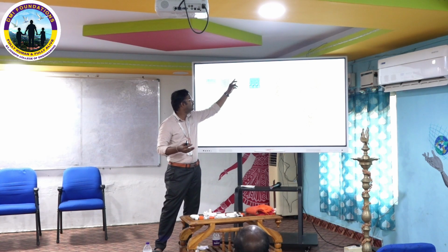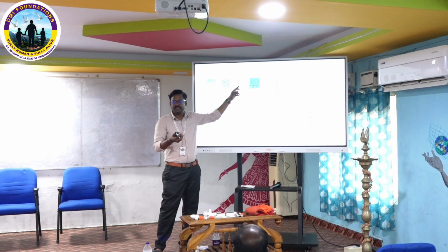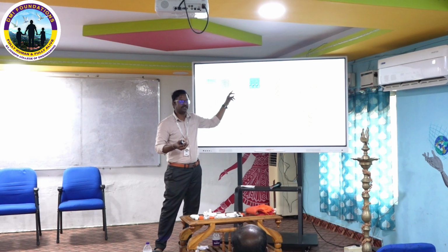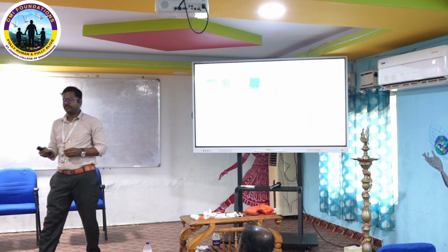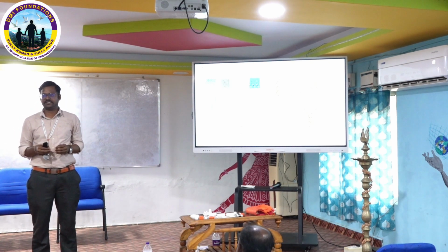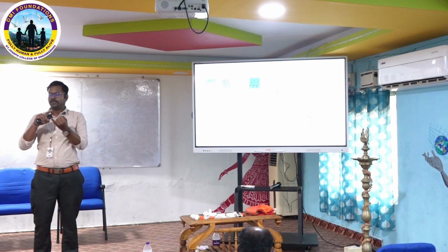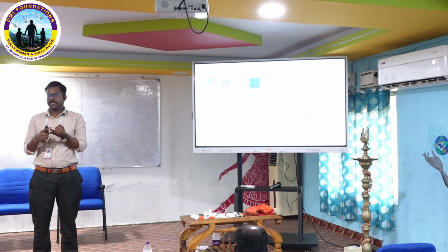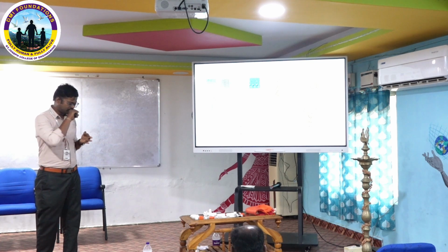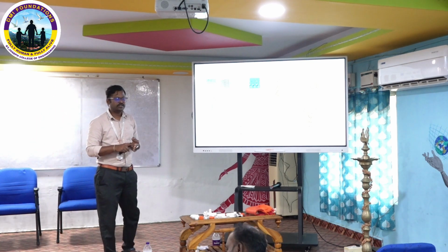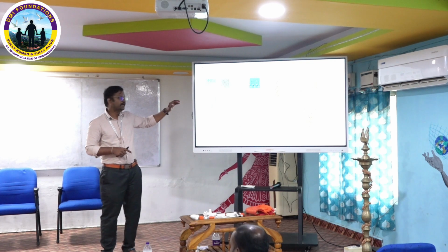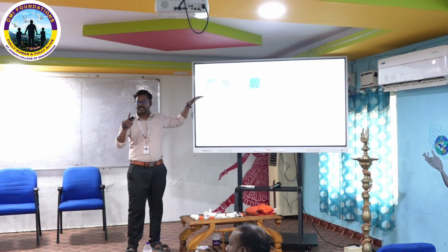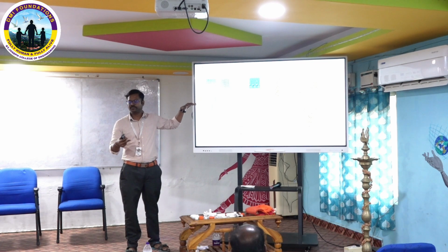So I will deposit my high strength lattices in the outer shell. In the inner shell I will use minimum relative density or minimum strength lattices. So it will give more material reduction and energy absorption, and cost reduction also. So these are the important applications of grading of lattices. Here we only incorporated single lattices with different volume, that means different densities.